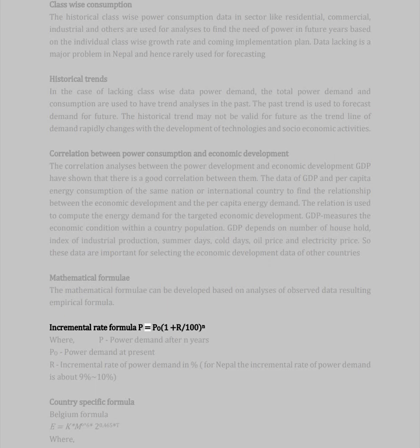Incremental rate formula: P = P0 (1 + r/100)^n, where P is the power demand after n years, P0 is the power demand at present, and r is the incremental rate of power demand in percent. For Nepal, the incremental rate of power demand is about 9 to 10%.